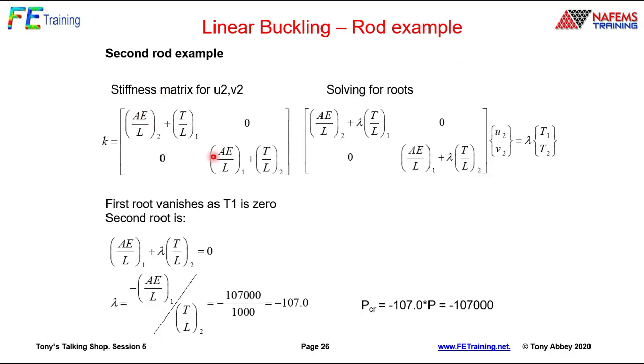If I write these equations out, so basically that's the stiffness. This is the stiffness times lambda, that's my deflection, there's lambda times my load. I can do a simple back calculation and say, when does the term go to 0? That term plus that term goes to 0 at that particular load level, and it's an eigenvalue of minus 107, multiplied by my load, then that's the value.